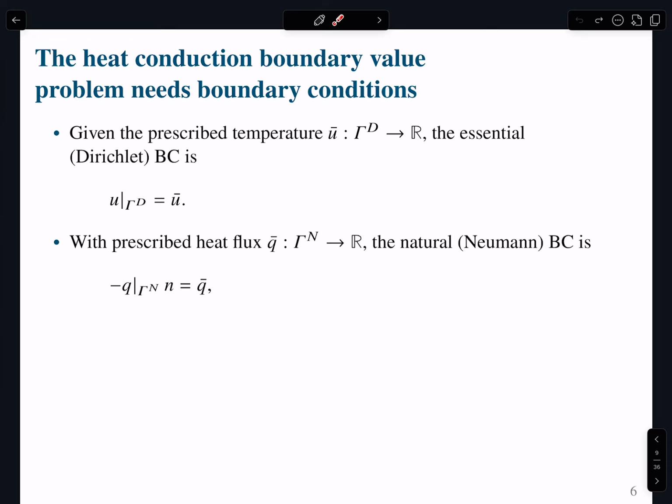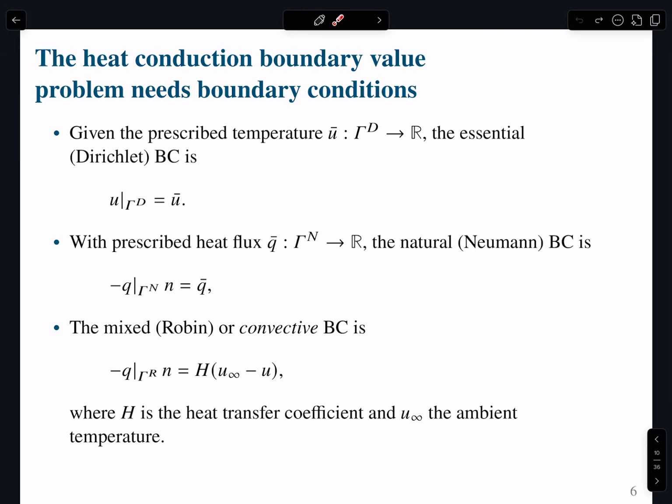If you recall, that n was used in elastostatics in 1D for doing what? Recall that? Yeah, it was to ensure our sign convention, that negative strain in the bar implied that your bar was under compression and positive strain tension, right? So we're going to do the same thing here, and we're going to analyze what this is going to be in a minute.